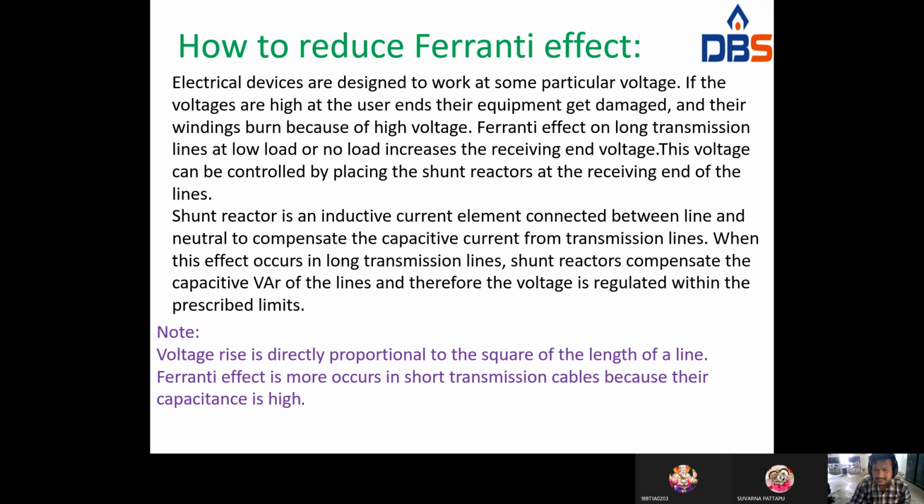What is the shunt reactor? A shunt reactor is an inductive element. It is nothing but an inductive coil that may be connected between the line and the neutral point, such that it will compensate the capacitive current.